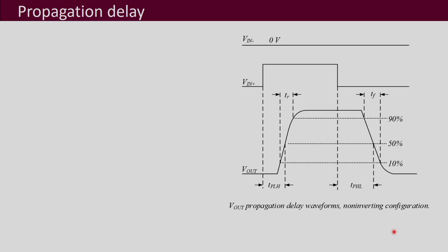one of the specifications that is important for gate drivers is your propagation delay. So, let us see what is propagation delay. Let us say you have this input voltage, and the reference is the 0 voltage level, which is explicitly shown here, and your input voltage goes from 0 to high.